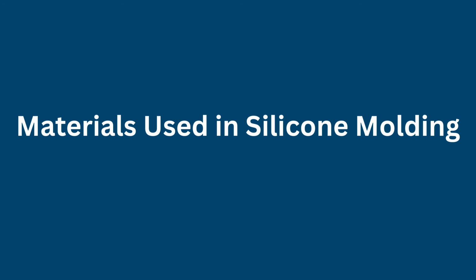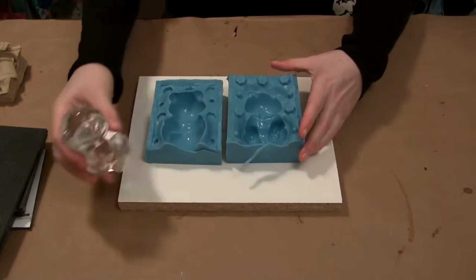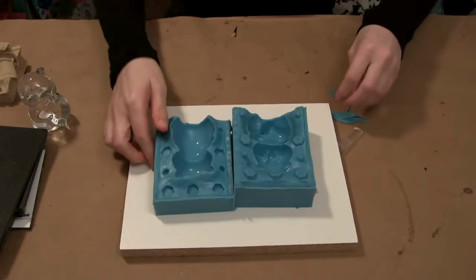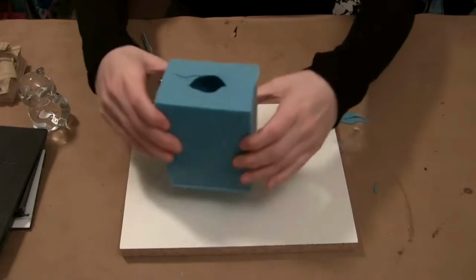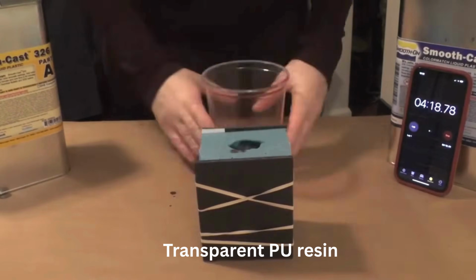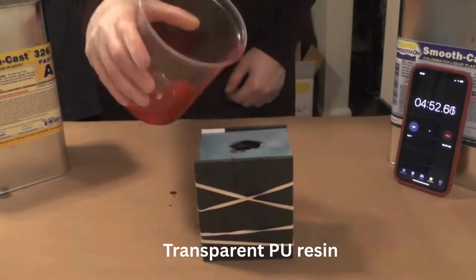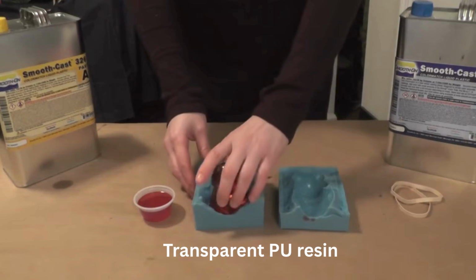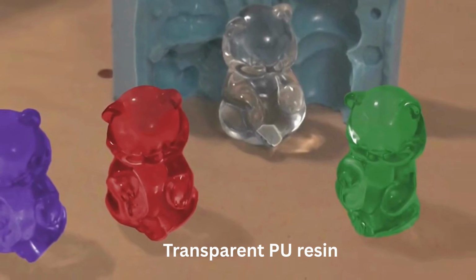Materials used in silicone molding. The mold itself is fabricated from silicone elastomers, whereas numerous casting materials can be processed within the mold depending on application. Polyurethane, PU, resins remain the most widely used casting materials because their formulations can simulate engineering plastics, including ABS, polypropylene, polycarbonate, nylon, and elastomeric materials. Flexible and rigid PU systems are available for appearance models and functional prototypes.